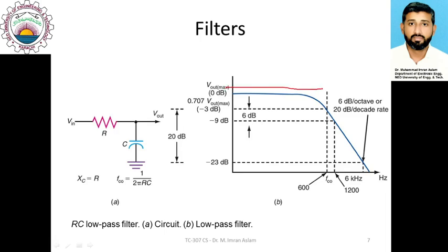As we know, this filter does not have a sharp cutoff frequency, so the rule that we use to calculate the cutoff frequency is the 3 dB rule. Whatever value you have here at the maximum point, whenever the amplitude is decreased by 3 dB, at that minus 3 dB point, whatever frequency is there is named as the cutoff frequency.